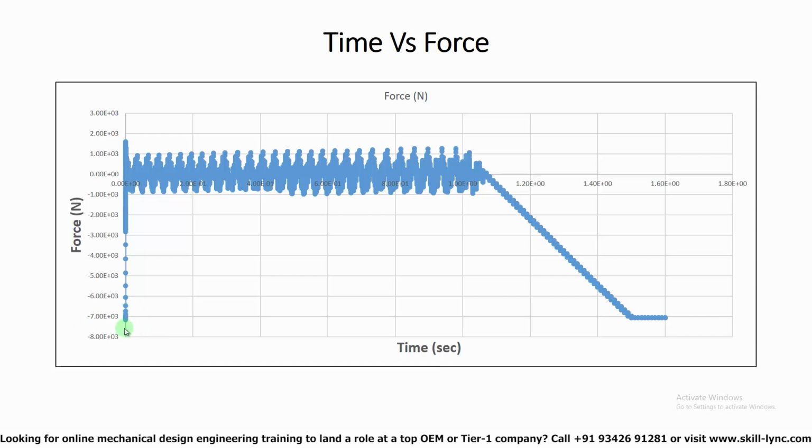Now remember, this is the initial force that's keeping the pressure valve closed, or at least keeping it at the lowest position, right? Now from this lowest position, what we are doing is we are running the simulation, and the fluid is almost imparting 7,000 plus newtons of force, and that is why the spindle is actually opening in the first place, correct? And it's kind of keeping it in that same zone, right? And that is why you see that your displacement profile also fluctuates, right?